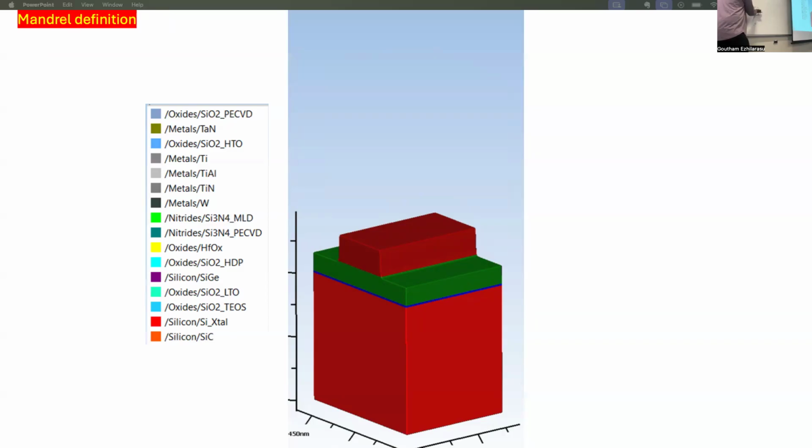Although I showed only this region, at some location somewhere here, it has an end. So when I create the sidewall spacer, it is located all around. But I want my fins only here and here. I don't want my fins here. So you have to open up a mask and remove the oxide sidewall spacer here, so that you don't have a fin at that region.